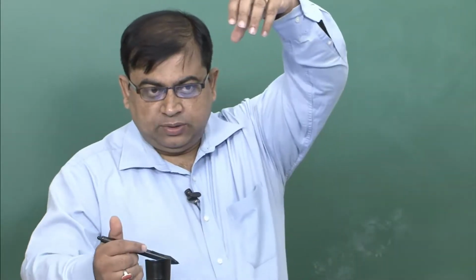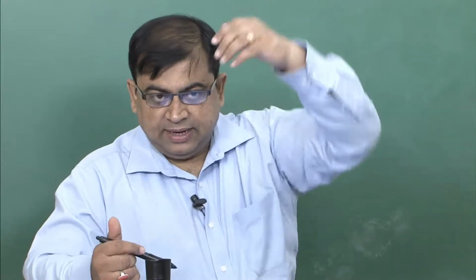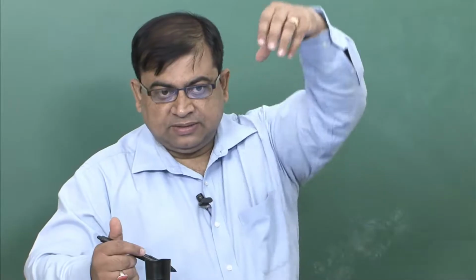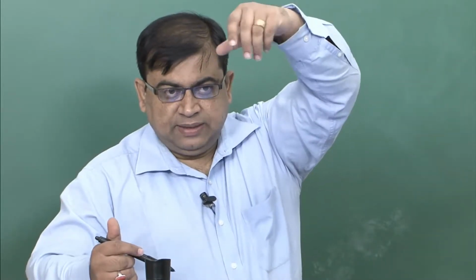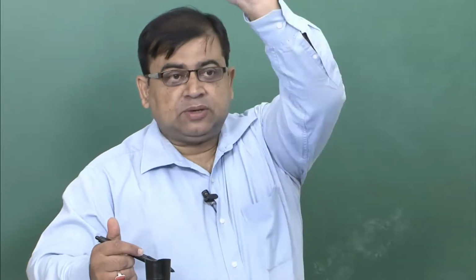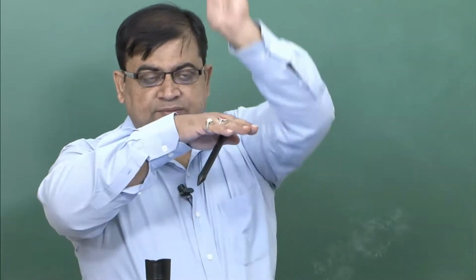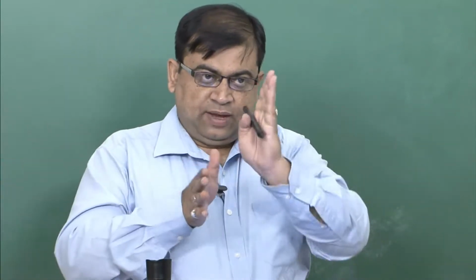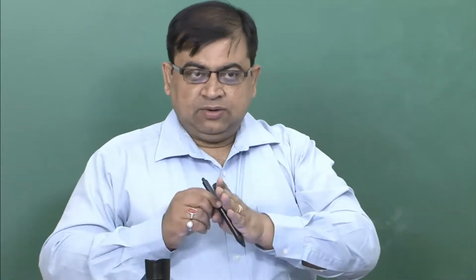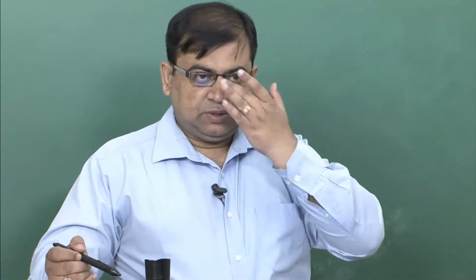If you look at the way the spindle is mounted, it is always mounted in some kind of column at the back end of the machine, away from the workpiece. With that column on board, if you are rotating the spindle, and this is the positive Z axis, going away from the workpiece in this direction, then to your right is the positive X axis. Obviously, if you have the positive Z and the positive X, you would automatically be able to ascertain the positive Y.